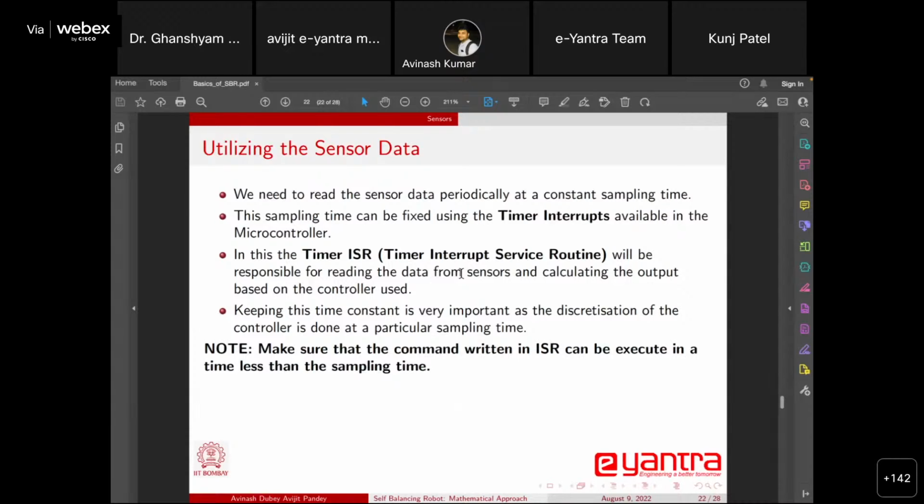There are timer circuits in the Atmega microcontrollers that we mostly use. Arduino Mega and Arduino Nano all have Atmega microcontrollers. These timer circuits keep count of every passing second. For example, if a timer has a resolution of 1000, within 1 second it will count 0 to 999, that is 1000 counts.